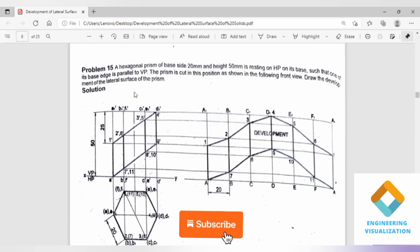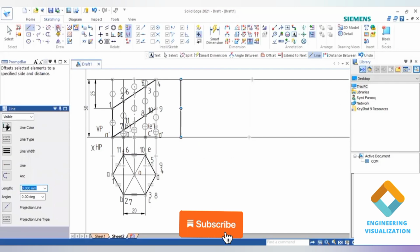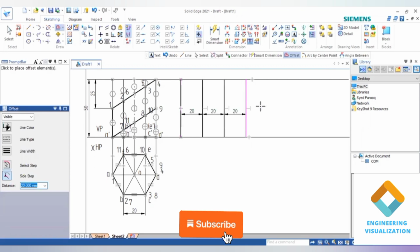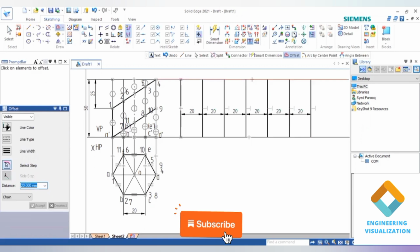You can see this is cut, so that means the front and top view will be given in the question. So we need to draw only the development for this. So vertical line drawn. Now using the offset command, I'll be offsetting this vertical line for a distance of 20 mm. There are total 6 faces I will consider here.